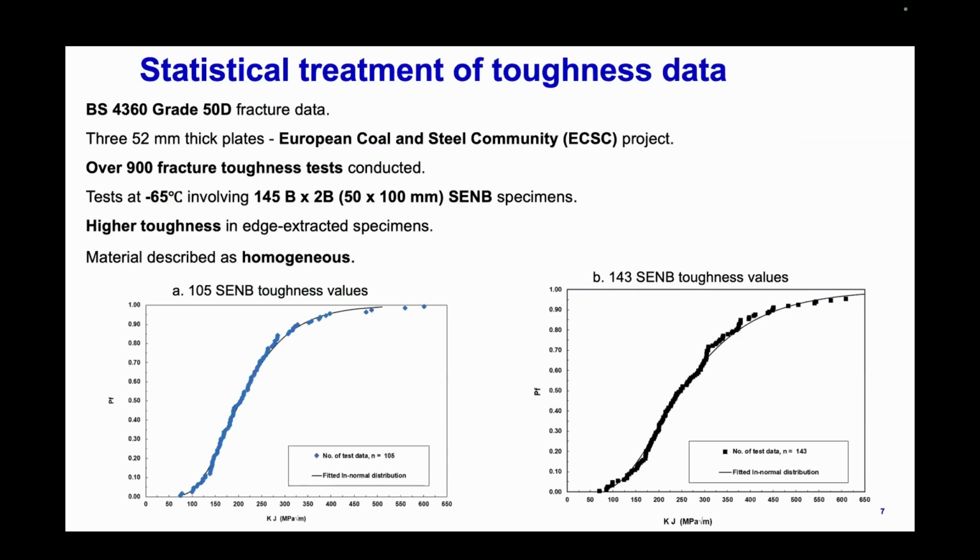And so we've done something similar to what BS 7910 advises, but here we use the 5th percentile with 75% confidence, which, with experience and research, has been advised as one of the good ones for high integrity components.